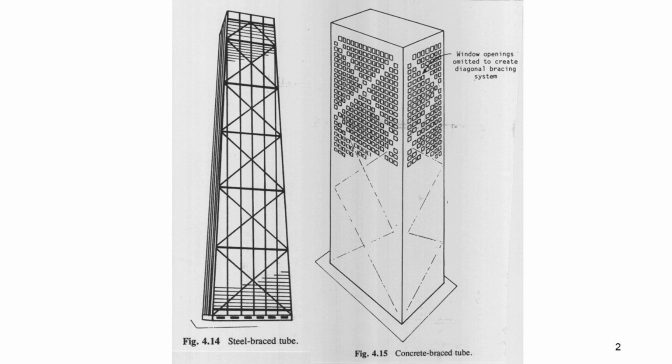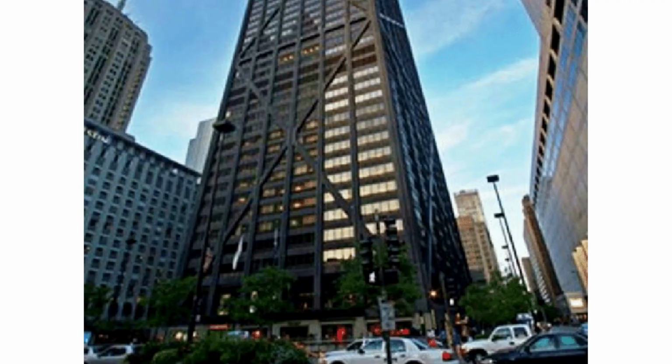This is another type of frame tube structure. We call this a braced tube. This system improved the efficiency of frame tube in increasing the building height. It behaves more like braced structure. The external brace improves performance of tube in carrying gravity load. Here is an example of braced tube structure, John Hancock building.